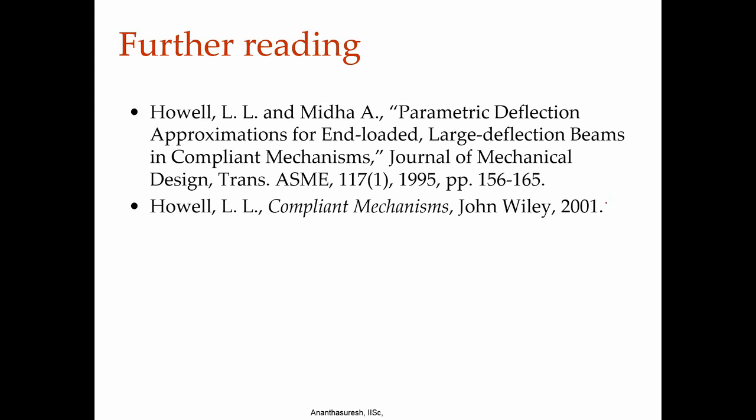If you want to refer to something further, I have given the reference to the book by Larry Howell as well as this fundamental paper that was published in 1995, which is worth reading, where they explain the details of how they fitted the curve, a lot of painstaking work after their initial observation that this torsion spring constant is indeed constant, pretty much with very little error, over a large range of rotation of the cantilever beam under inclined loads of all kinds: compressive, tensile, axial loads and transverse loads together. This will lead to this nice elastostatic approximation.